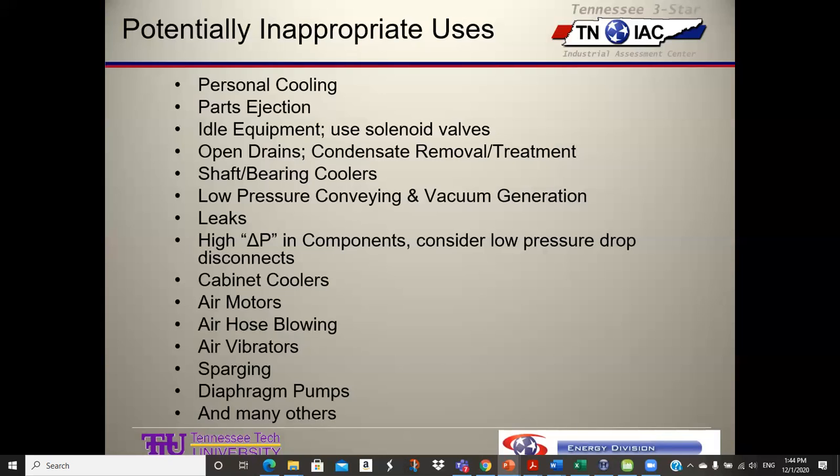Air motors, they're very convenient. People use them to stir paint in barrels, to pump slurries, all kinds of stuff. They're very portable. You can carry the thing up, set it down, put a couple concrete blocks on it to hold it down, hook up your lines to it and your compressed air, and bingo, you're pumping. So you don't have to pull electricity to it and conduit and all those sorts of expenses. But again, compressed air is expensive.